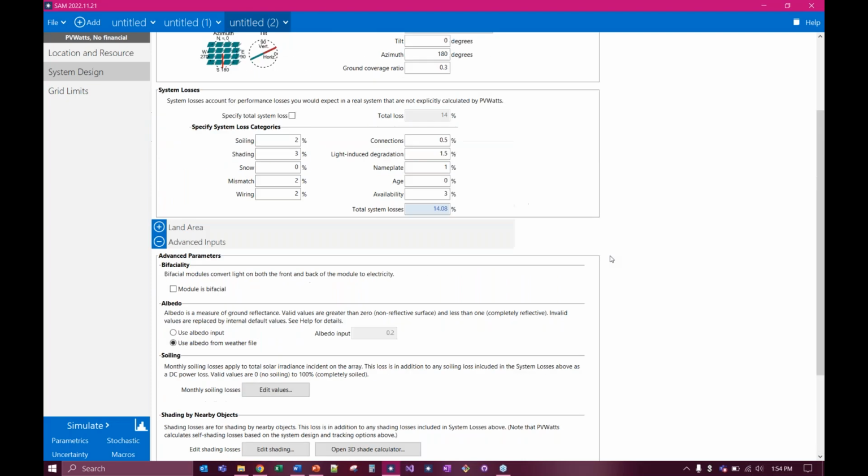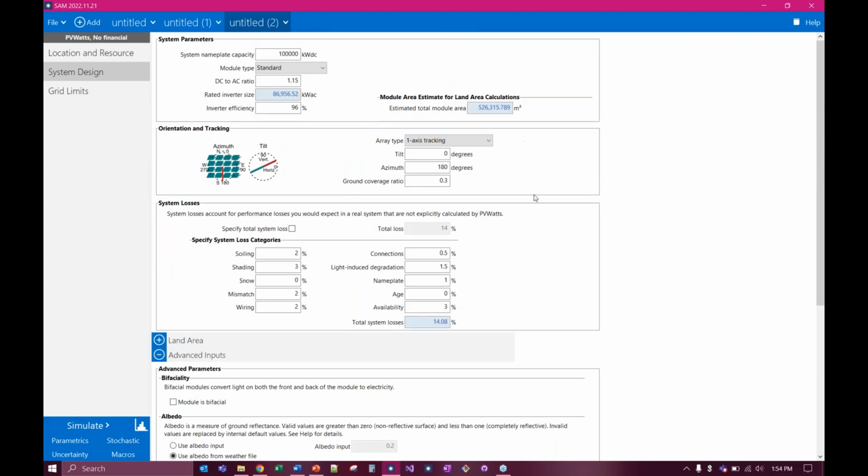And the biggest difference that you'll notice is that there's no information about the electrical layout of the system. And that is, again, because we make some assumptions for a pretty regularly laid out, reasonable electrical design on the system that isn't going to do a bunch of clipping or anything like that, other than power clipping if you were to specify a pretty high DC to AC ratio.